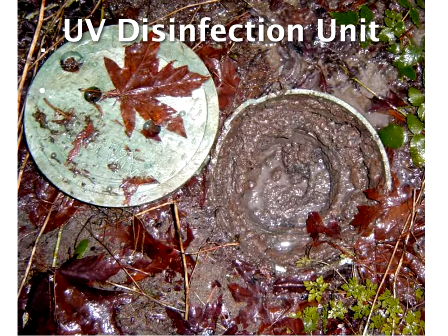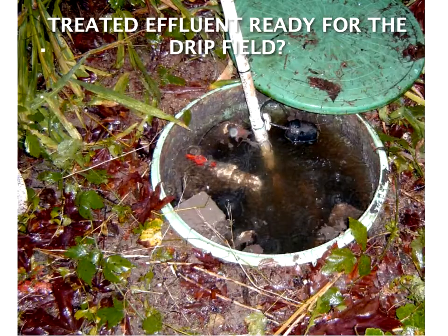But continuous chlorine injection is going to go through and kill the bacteria in the soil. And the aerobic bacteria in the soil are our allies. These are our friends. These are the ones consuming the anaerobic bacteria that are coming through. And I just think that it damages the natural treatment cycle in the soil. If you like, you can talk to David Morgan more about that, as he's our soil scientist.